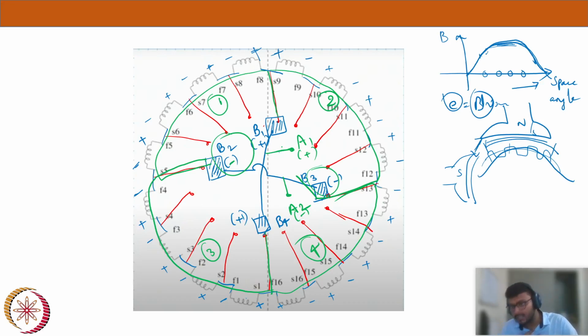Now what my intention is, whenever a current is flowing through brushes, two brushes are there, positive and negative, the current is getting divided at the armature into four parts, to B1, B2, and after getting into B1, it is again dividing into two parts, B1 to B2 and B1 to B3. That is, another part is, when it comes to B4, it divides into B4 to B3 and B4 to B2. Now how many parallel paths are there in total? Four parallel paths.